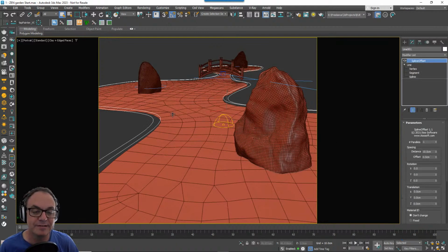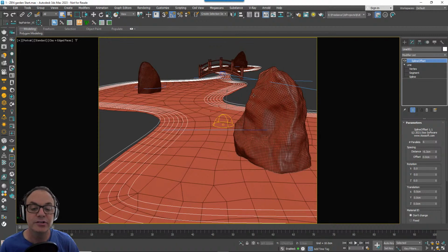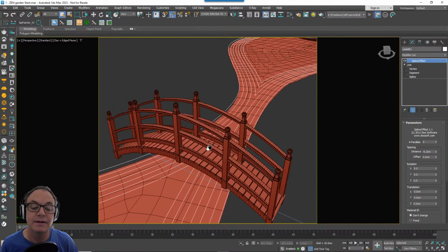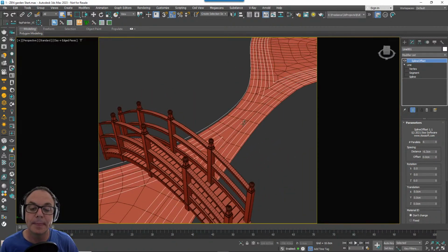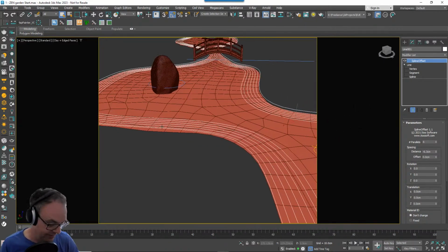So what this does basically, as you can see here, is it adds an offset around the chosen spline, parametrically, a set distance. And if I make this a negative distance, it will start to come in instead of going out. So I can go for about -6-ish, something like that. I can choose how many times I want to offset that. Now, one quite nice feature of spline offset is that when splines intersect, like they have done here, it automatically heals them. Okay, so it automatically cuts them together and not overlapping, which is nice and will give us a nice kind of look down there.